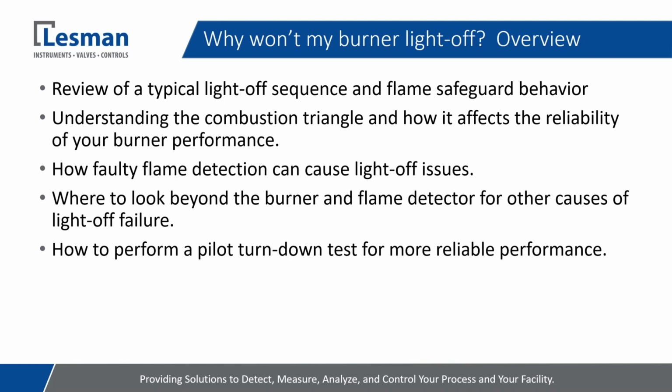because we're dealing with combustion and trying to get combustion to occur. We just wanted to do a quick review of the combustion triangle and how it affects the reliability of the burner. Because we are using flame safeguards and different types of flame detection, I just wanted to also review those and how different issues with the flame detection could cause us some light-off issues.